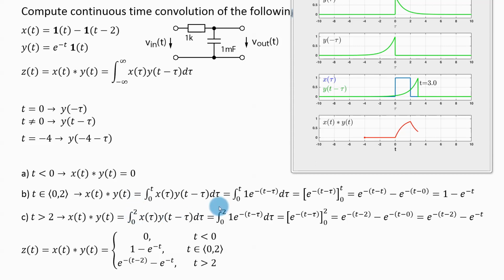Now, one thing to point out: the discrete convolution, which we had previously, is something which is actually being computed when you implement the filter. When you want to filter, for example, your music, the discrete convolution can be something which MATLAB is going to be computing. But when you have a continuous time circuit, you can describe it using a convolution, but this circuit is not actually computing the convolution when it is taking this input voltage and creating this output voltage.